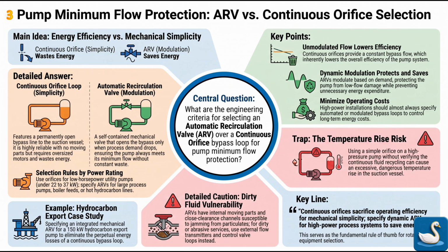It really is. True engineering expertise isn't just opening a manufacturer's glossy catalog and taking their data curves at face value. Right. It's about understanding the raw physical realities hiding behind those curves. Exactly. Knowing that the vendor's required suction line mathematically guarantees a 3% performance failure, or recognizing that operating at the edge of an allowable region will slowly, methodically vibrate a multi-million-dollar machine to death over time. It's about fiercely protecting the equipment's lifespan over short-term capital cost savings.